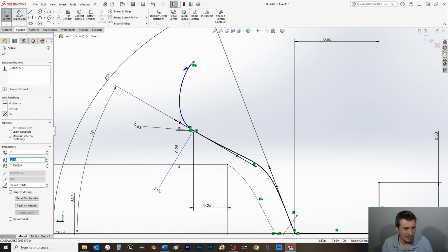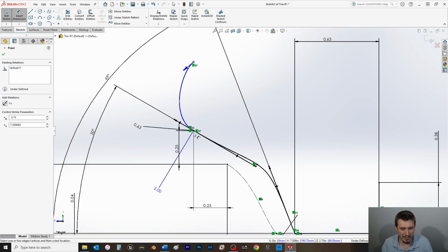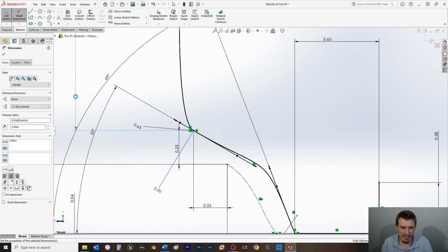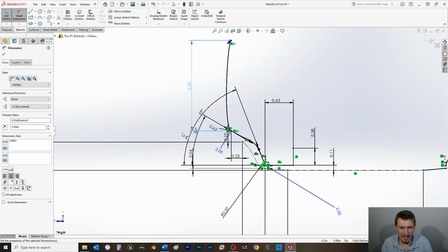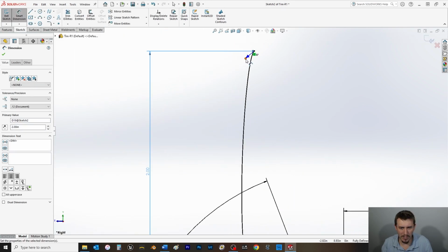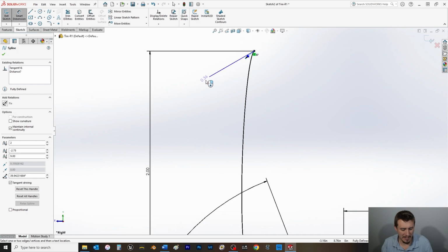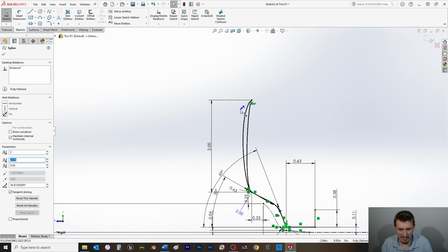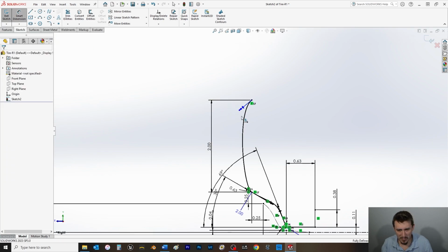Let's add this dimension in here first. Kind of the tire wall height. Probably want it to be about 2 inches. Let's bring that out. Yeah, something like that'll work. And then let's zoom it out, drag the handle, see what we got here. Sure, something like that. So with that, we'll add a smart dimension.